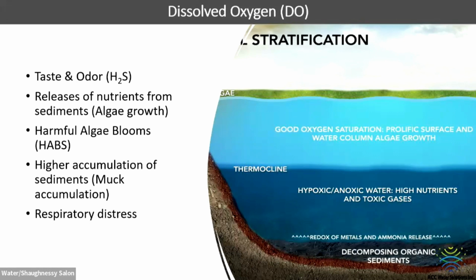It's pretty clean. You get nutrients coming in from your watershed source or whatever your source is, and they drive some productivity. You start getting some algae, some weeds growing. And then those algae and weeds die and they settle to the bottom and they increase the oxygen demand. And that causes the next year even more productivity in your pond, because now we've got that redox starting to happen, and it builds up over time.